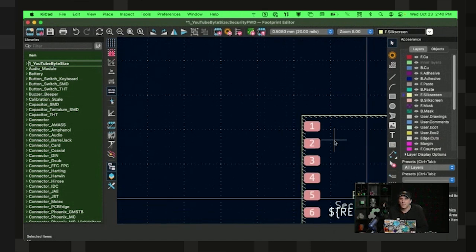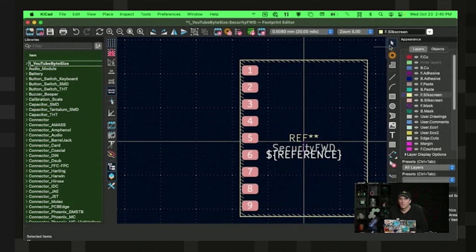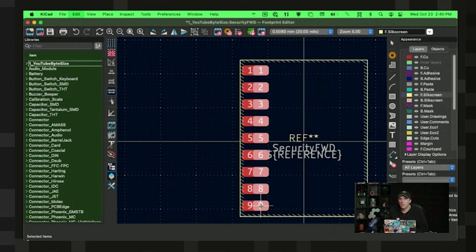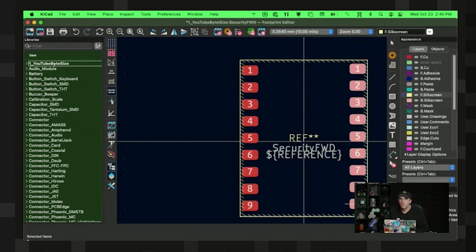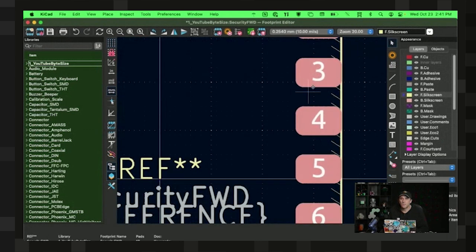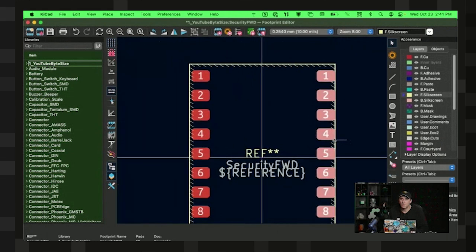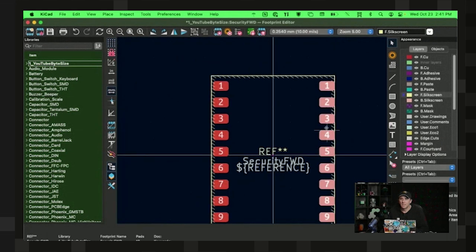So, all right, now I have the other side to do as well. And what I'm going to do is be lazy. So I'm just going to take this, select them again, copy, and paste them. And look at that. So now, provided I'm snapping to the same 2.54, okay, now that I'm still snapping to this, if I come over here, oh, I can get closer on this side. All right. Well, this is more what I'm looking for, basically kind of touching the side, and KiCad might not like that. We'll see if it doesn't like that, but that's kind of the idea here. So let me try moving it in just so it's symmetrical. All right, so that's where we are for now.